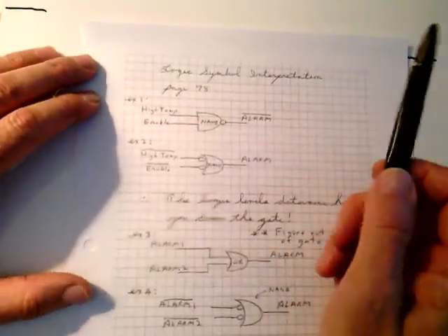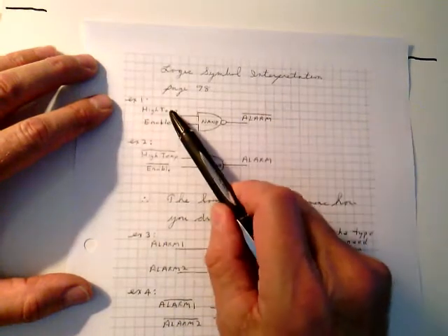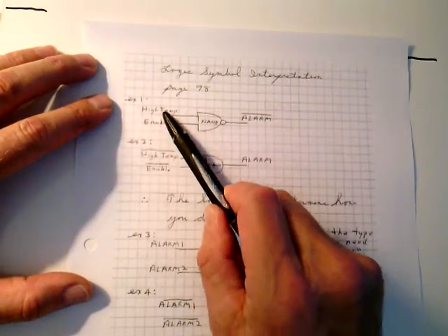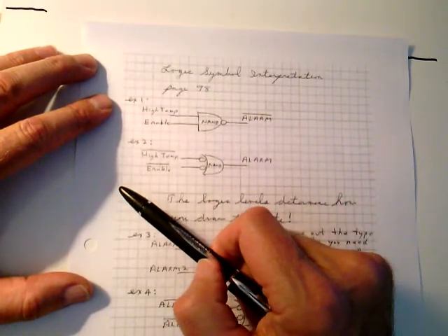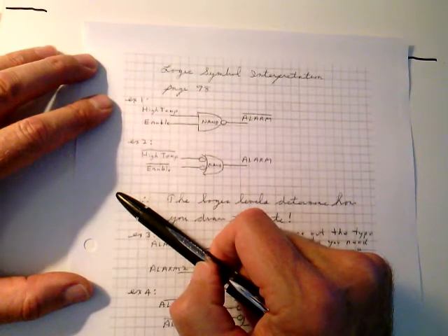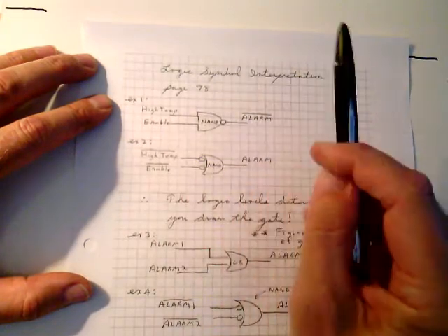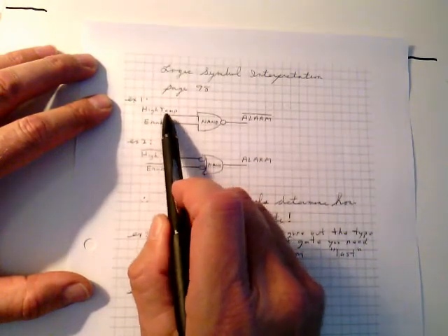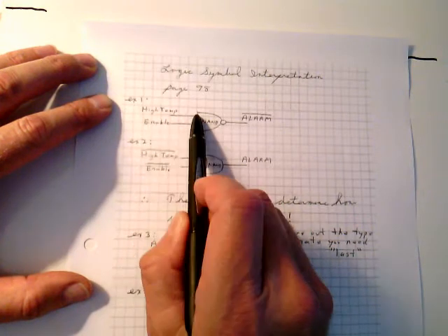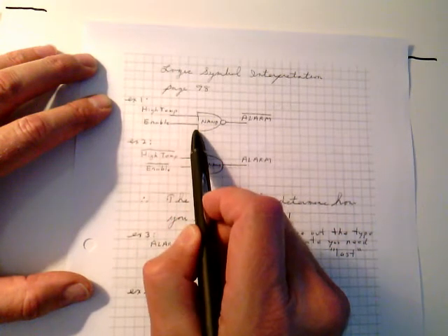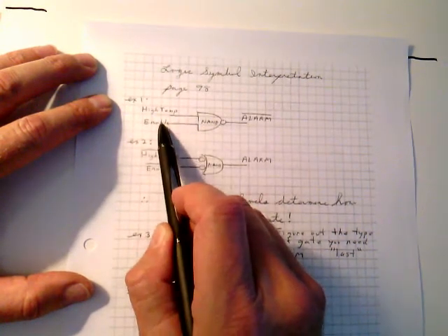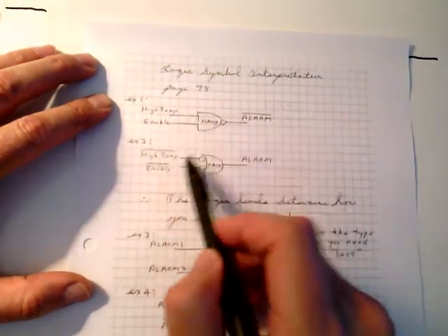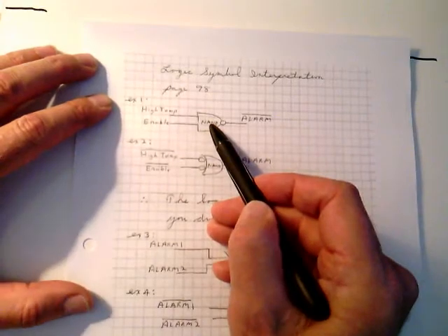Let's say in a specification they tell you that you want a high temperature signal and an enable gone high, and when that happens you want a low output. Well, you just draw the gate. You draw what you need. So the story here is, in the specification, it's going to say, when I get a high temperature and I get a high enable, I want the output to go low. And you just draw what it is you need, and you look and say, what's an AND gate?